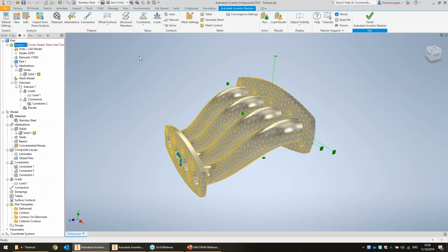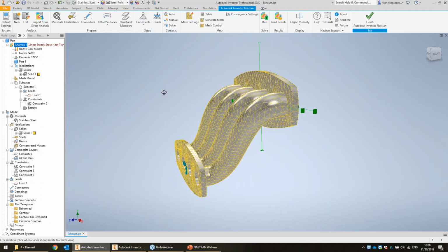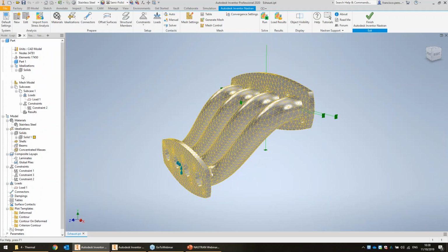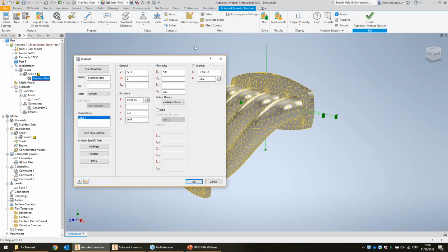The problem can arise that you will have significant airflow. So say, for example, you've got a fan blowing over the exhaust, and unfortunately, Nastran can't calculate the airflow and the subsequent effective convection coefficients. If you wanted to do that kind of analysis, you'd have to step it up and get Autodesk CFD, which deals with fluid dynamics, and it'll allow you to do airflow and currents and heat exchanges and whatnot.